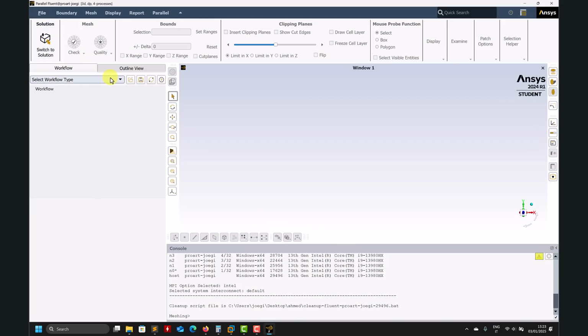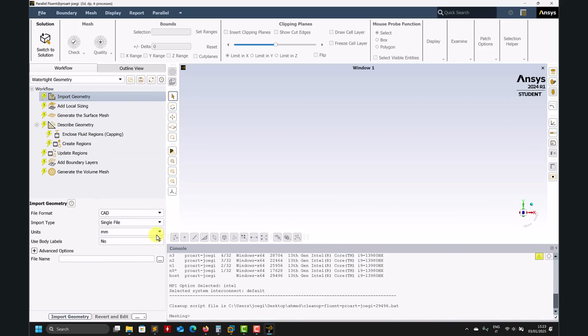Okay, so here we go: watertight, import geometry, meters, let's select. To point out here, you also have options. Things can be a little bit tricky, but similar to what we do, recall in Snappy, that you can do a separate by zones and you can give an angle for regions. You can do something similar here. So it's not only limited to Snappy, normal tools do that, but usually you have the CAD, you have all that subdivision. So that would be something that you will do if you have dirty geometries. You can have multiple files.